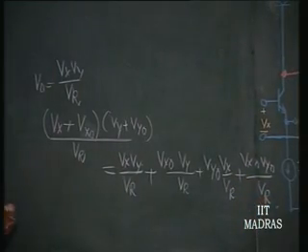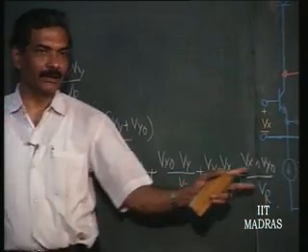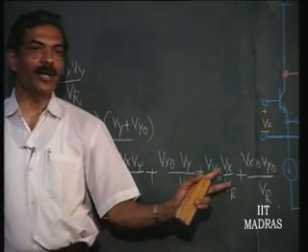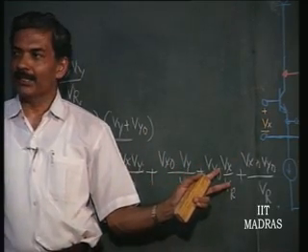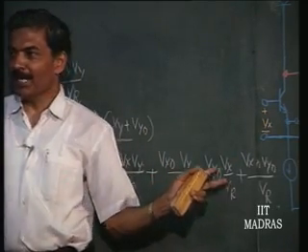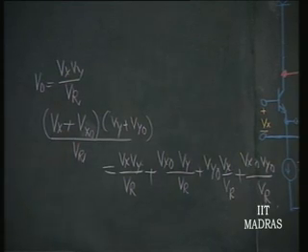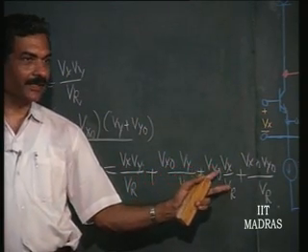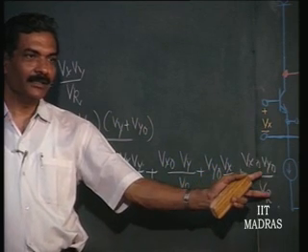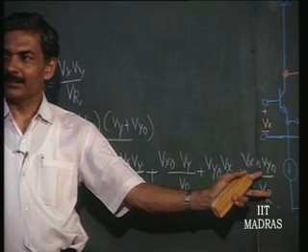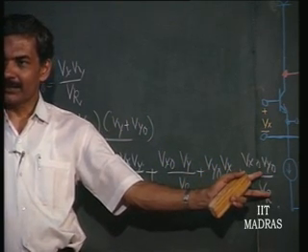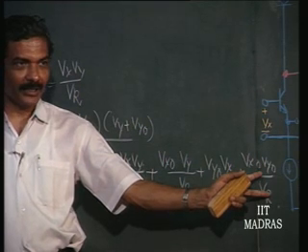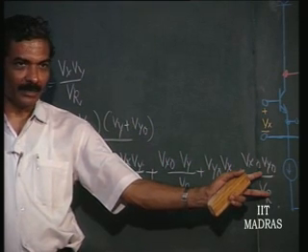Obviously, these are unwanted terms. These are the two feed through components which have come out. Because I have introduced a DC offset, we have got unnecessarily V y feed through and V x feed through and DC offset. So, now this is behaving like a non-ideal output in the case of a multiplier.